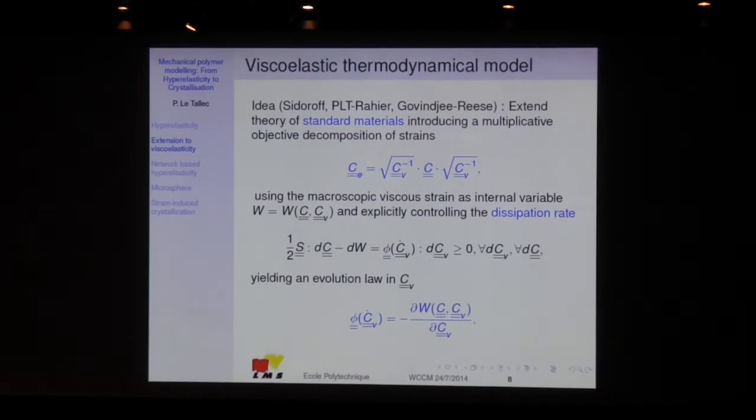But apart from this little technicality for anisotropic materials, the situation then is quite simple. You have an additional internal variable, which is the plastic strain rate, and you explicitly try to identify the dissipation in any evolution. Once you do that by postulating some kind of dissipation law, you automatically have the evolution law on the additional internal variable, which will guarantee this type of dissipation. So it's really a dissipation-controlled evolution law that you can build. And then the idea is to find the right form of the dissipation here.